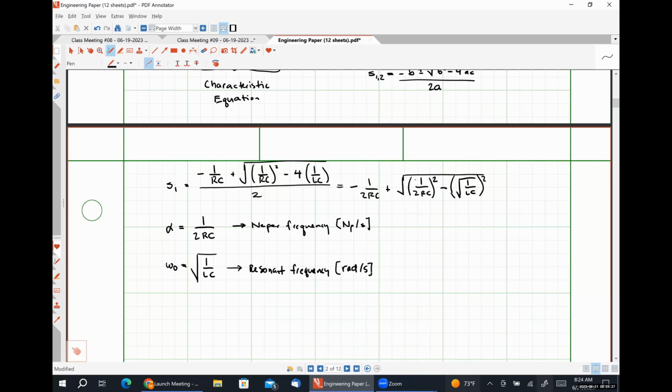So in most electrical systems, the resonant frequency means two things, and it means both of these things effectively at the same time. The first of which is this is the frequency at which the system will resonate with the largest amplitude for the smallest amount of input energy.